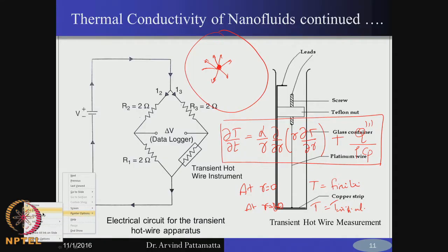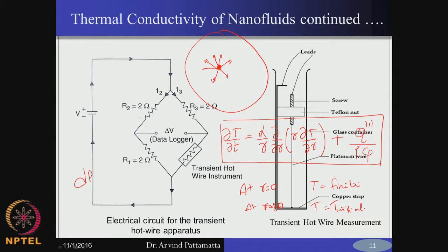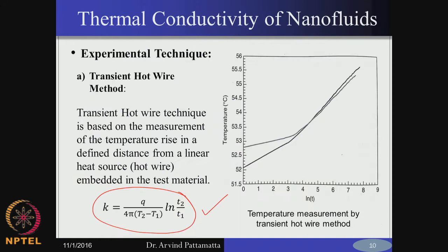Okay. So, therefore, you know dR/dT, right. So, you know the value of R. So, if you plot R versus T, suppose this is a linear relationship, you have a constant value for the slope. So, for this value of resistance, you know the corresponding value of temperature. So, like this you plot temperature as a function of time. So, it is nothing but resistance as a function of time. And this resistance is changing because the wire is getting heated up, you are continuing to supply heat.